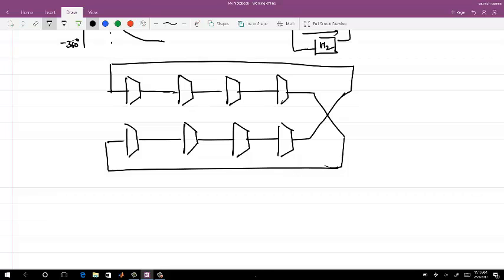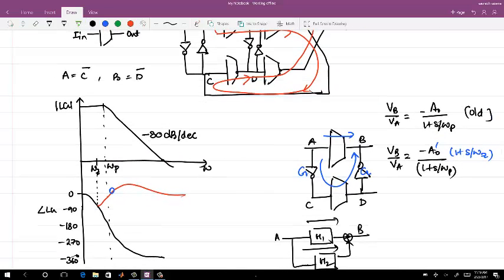So with single inverters, you can try it out. How many zeros does it have? Because if you are having single inverters, you will not have the same transfer function from the input to the output of each cell. Your transfer function will change. You got that thing. The placement of the zero, when I have these two cross coupled inverters, I can write the same transfer function for each input to the output. This is identical.